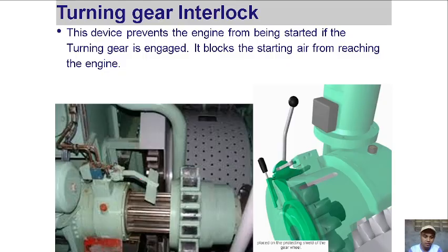And then after using the engine, you should also practice engaging the turning gear to prevent any sudden starting of the engine.